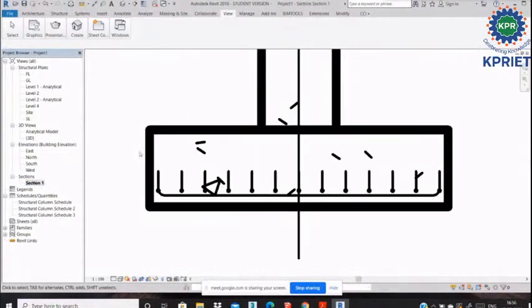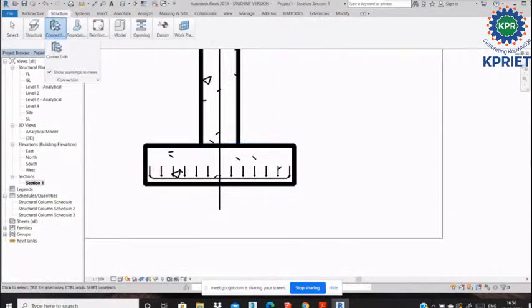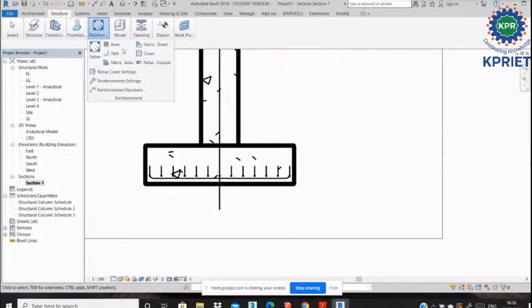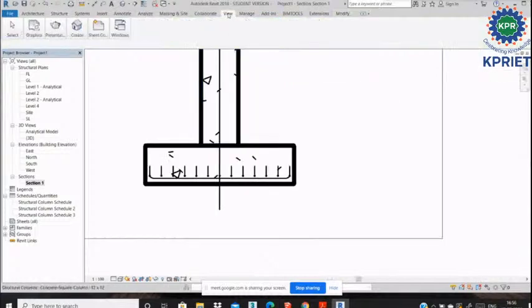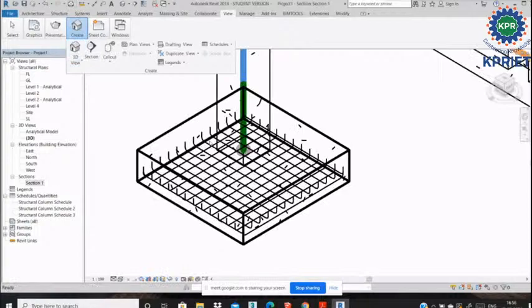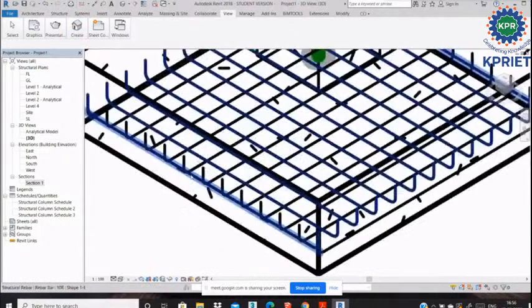So simply select your rebars, then go to structural, sorry, reinforcement, click the rebars and go to reinforcement, then click the reinforcement, go to place a work plane or reference plane, then go to rebar set. Single means single. Maximum, you give maximum spacing. Simply click the maximum spacing. You go to that length. Automatically it will calculate the spacing. Now see, automatically it will be created, the reinforcement, right?